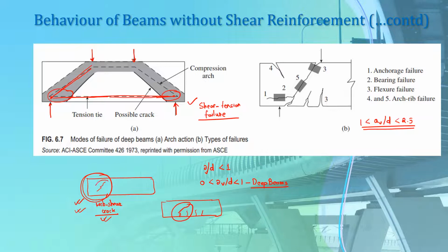So these are generally not desirable. But these flexural shear cracks, these are the most common type found in reinforced concrete beams. So these flexural cracks extend vertically into the beam, then an inclined crack starts forming from the top of these vertical cracks where shear stresses develop, and these propagate into the beams in this way.